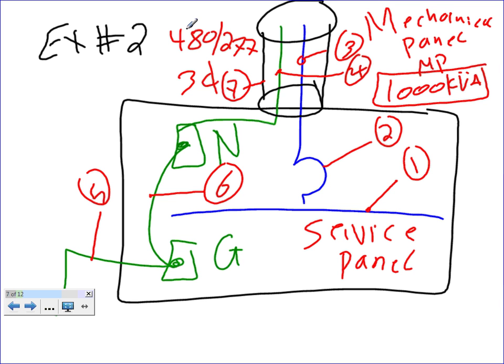So they want to make sure it can handle the neutral load upon the loss of a neutral. Say I had a storm and I lost my neutral only. If I'm bonded, then all the neutral current will go through the bonding jumper down to Mother Earth. But you will have multiple number 5s, but only one bonding jumper. So, good point though.